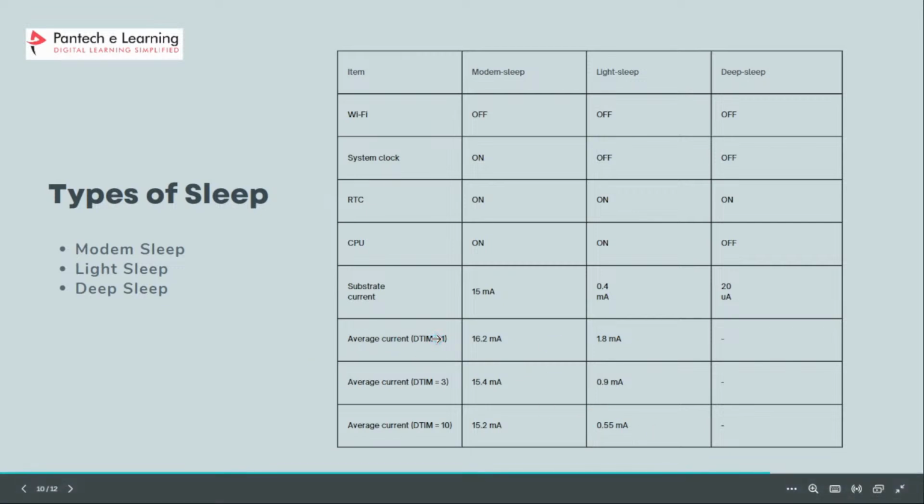The table provides an estimation of average current consumption in milliamperes for different scenarios, assuming the microcontroller is operating at a 3.3 volt power supply. The lower current in deep sleep mode signifies minimal power consumption, which makes this mode suitable for battery powered devices. But power conversion is a crucial factor.